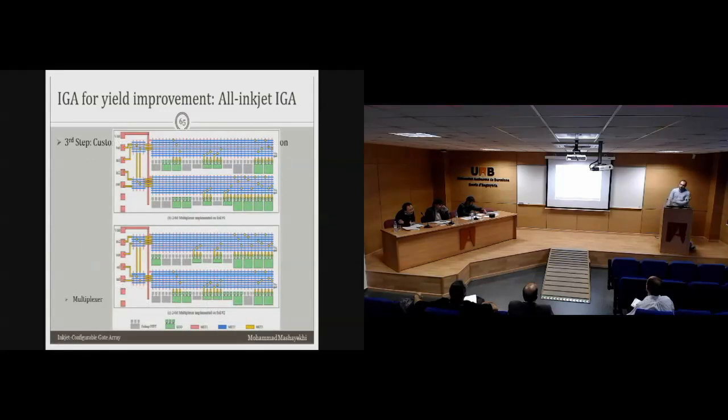Yeah. The reason is that for this technology, we have enhancement mode transistors with negative threshold voltage, which lead to a diode connected load topology. So for that, we connect the gate not to the drain, but to minus VSS. Ah, I see. Okay. So this is why we have 3 power rails. So you have 3 rails for this. I see. Okay.